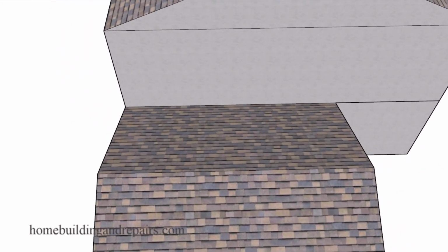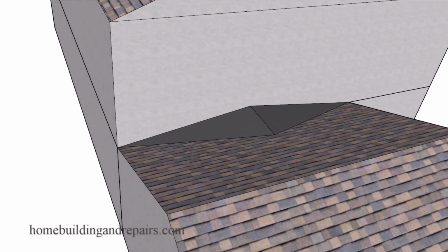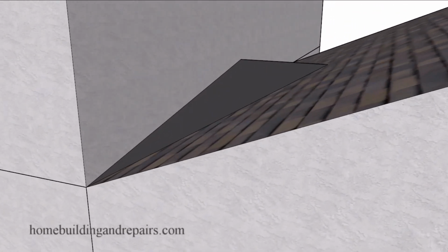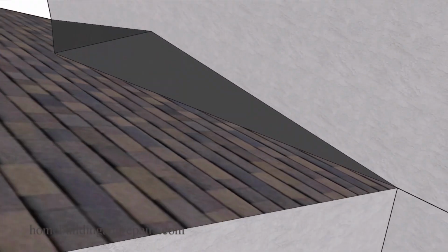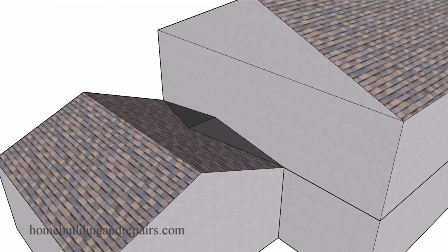And in my first suggestion, I would suggest installing a roof drainage cricket. This is probably going to be the cheapest and easiest one to build. However, it could trap a lot of snow if you live in an area where it snows a lot. And you're simply going to create a slope on both sides so that water can drain off of the roof. And I do have other videos on how to build a roof drainage cricket, and I'm sure those can be found at our website or by simply typing in roof drainage cricket into your favorite search engine.